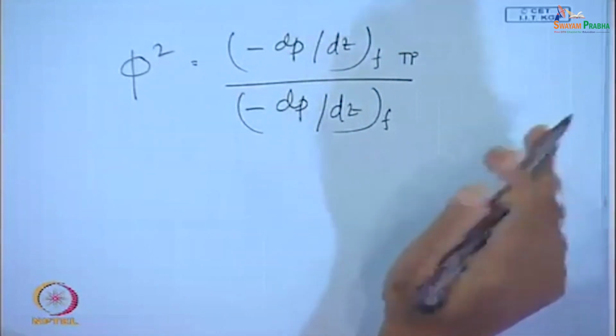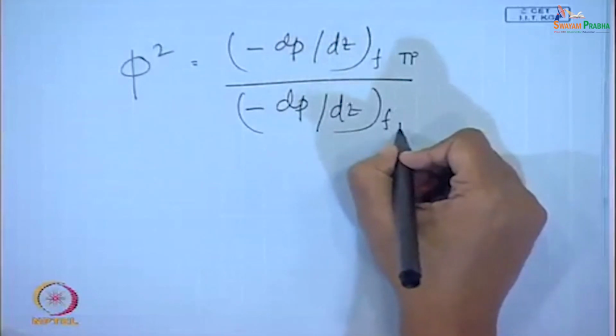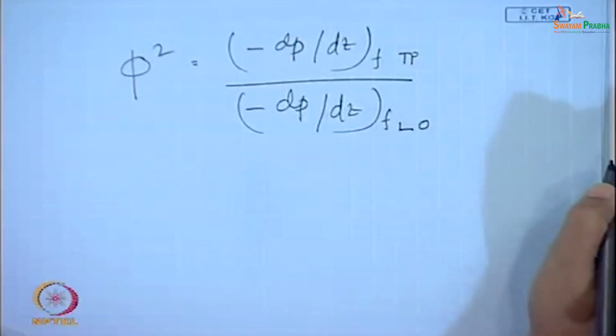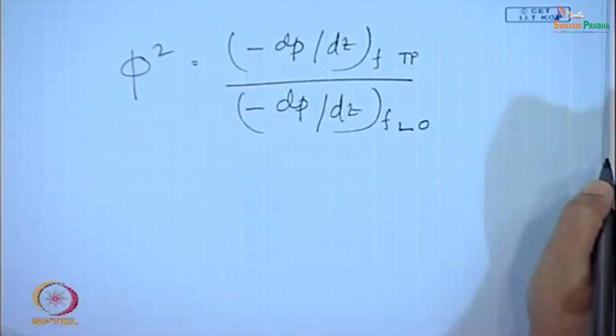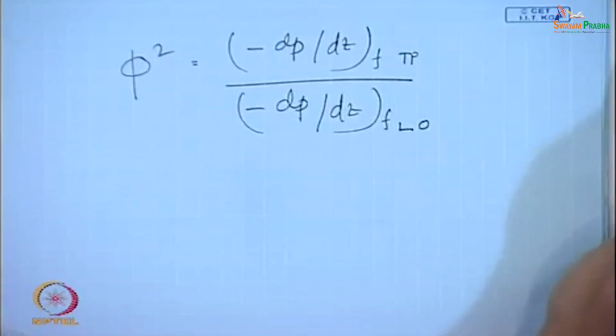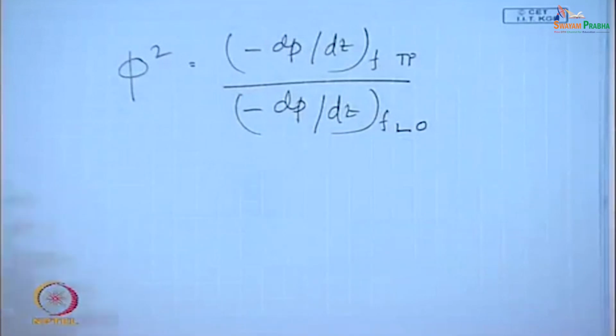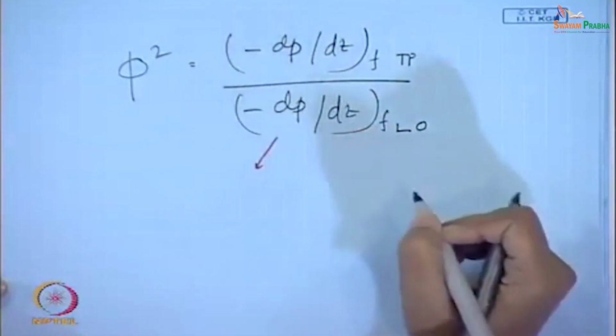Now, remember in this particular case, we can define 4 different correction factors. How? One is in terms of when the entire mixture flows as liquid. Do you get the point? Which we have been doing so long. When the entire mixture flows as liquid, what is the expression of this frictional pressure gradient?